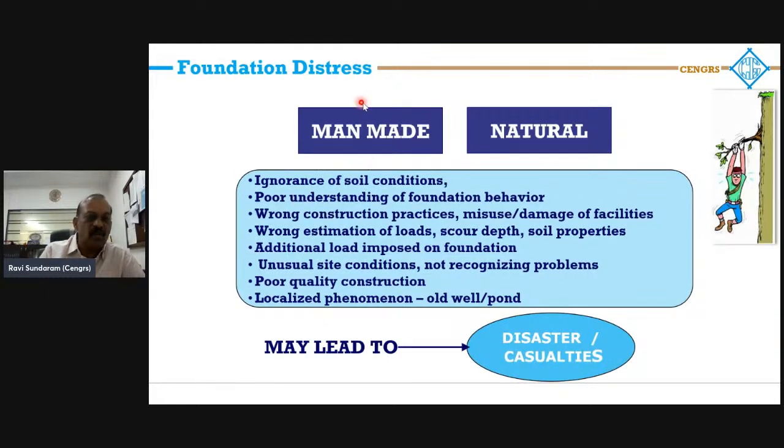So distress, as you know, could be man-made or natural. So we are talking of several possibilities, like ignorance of soil conditions. You didn't investigate the soil condition properly. Poor understanding of foundation behavior, wrong construction practices, misuse or damage of facilities, wrong estimation of loads, cover depth, or soil properties. Additional load on the foundation was not taken care of, unusual site conditions not recognized, the problems.